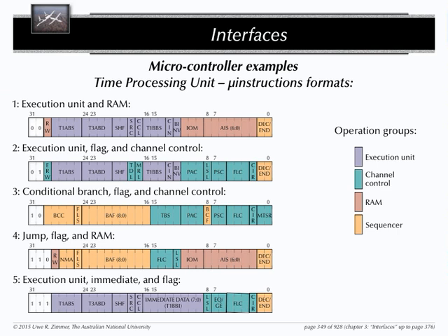What's the benefit of having this compared with having 8-bit instructions and 16-bit instructions and more of them? You're losing a lot of performance because you can now only do this sequentially. If I break this down into little 8-bit instructions, then I have an instruction which does a sequence operation, a jump.